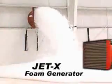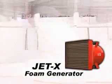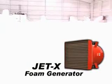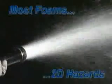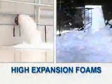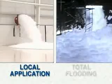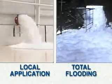Just one JetX 15 foam generator can produce a volume of expanded foam at a rate of nearly 20,000 cubic feet per minute, depending on inlet pressure. While most foams can only be used for two-dimensional hazards, the high volume output of high expansion foam systems enable both local application and total flooding protection. In fact, because of their unique capabilities, the National Fire Protection Association established Standard 11A specifically for medium and high expansion foam systems.